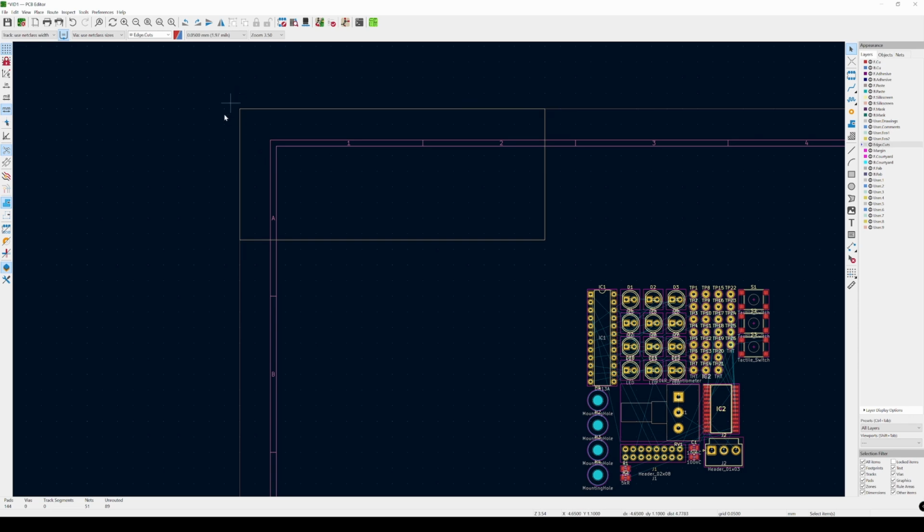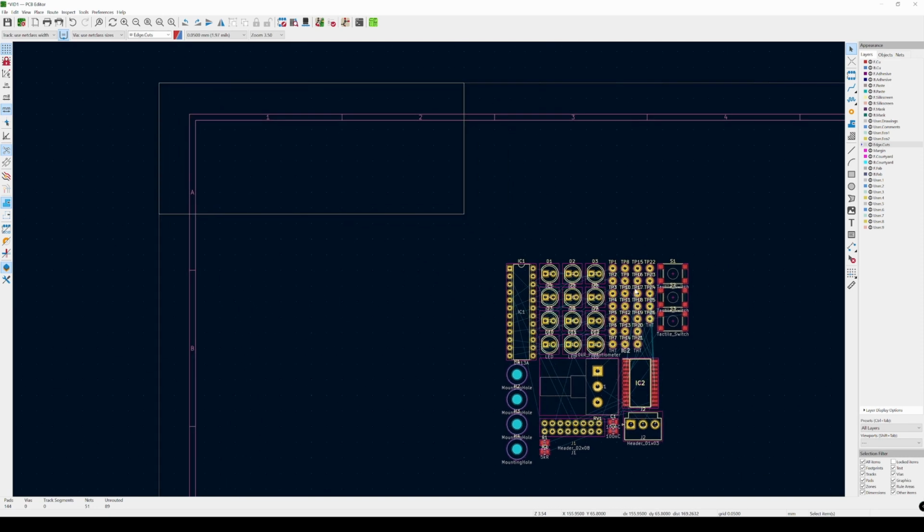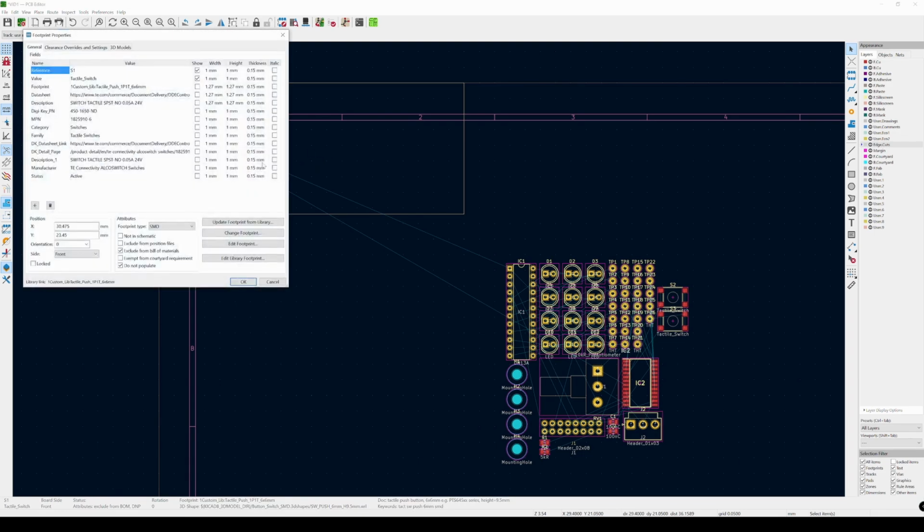the reason that I want the PCB to start from the 0 corner is so that now that I'm gonna be picking up my tactile switches, I can double click the component. It brings me this menu, footprint properties, and down here we have position.